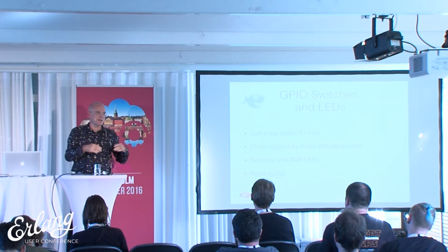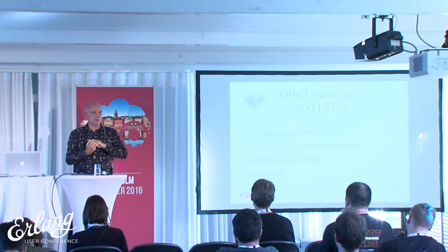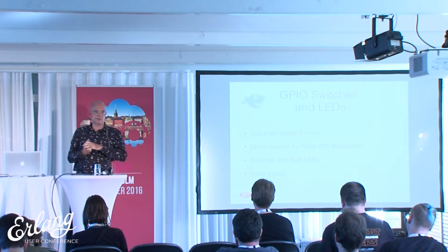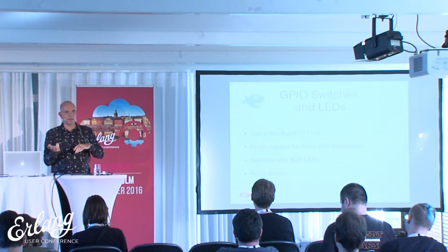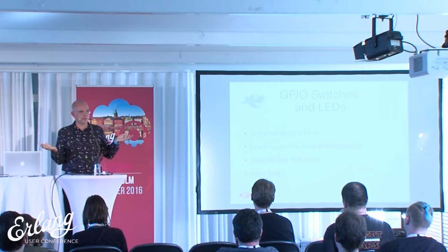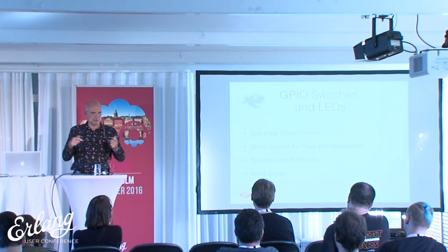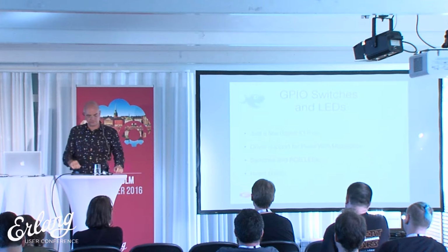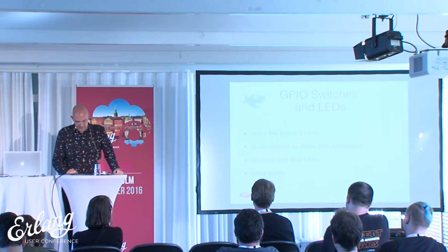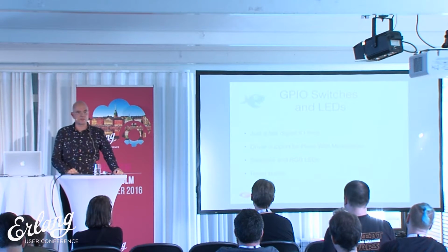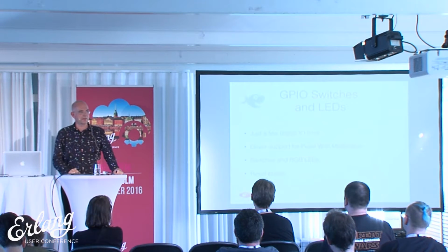So every LED has 3 IOs, one for every color. And if you do pulse width modulation, you can get all the colors that there are. If you only switch on and off, you only have 8 colors. I mean, 7 colors and none, or off. There's also a reset button, because it's convenient if you can just reset your thing if you crashed it.